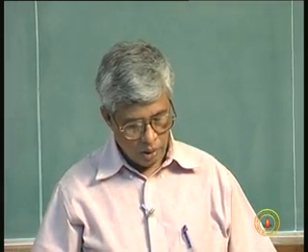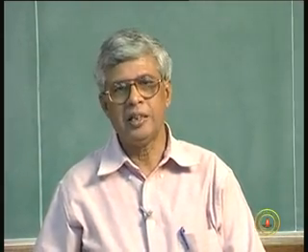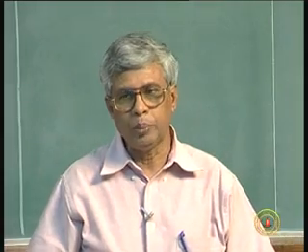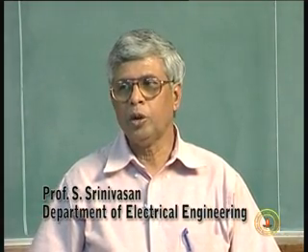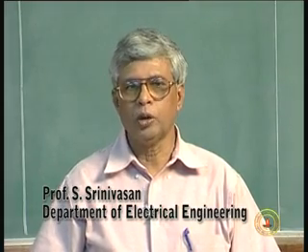So, we talked about Moore machines and Mealy machines based on the outputs. In a Mealy state graph, the output at any state is defined by the state and an input. So, in a given state there can be more than one output because there is more than one input possibility. On the other hand, in a Moore machine, the output is tied to a state. A particular state will have only a particular output, and the output will change only when the machine changes from that state to another state.